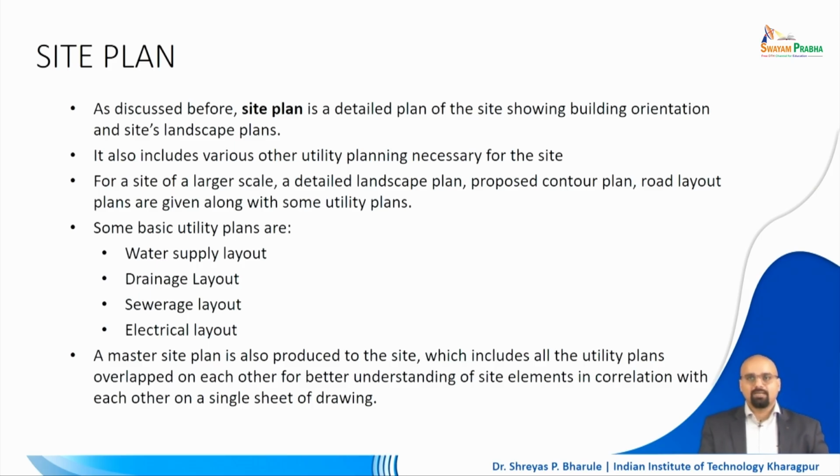So, you need to be careful, and there should always be a test done before you deliver all of the site drawings to the consultant, to double check that there are no or very minimal layers of overlap. If there are overlaps, certain interventions are taken care of, such as putting the water supply line much lower or much higher compared to the drainage layout, and so forth, right.